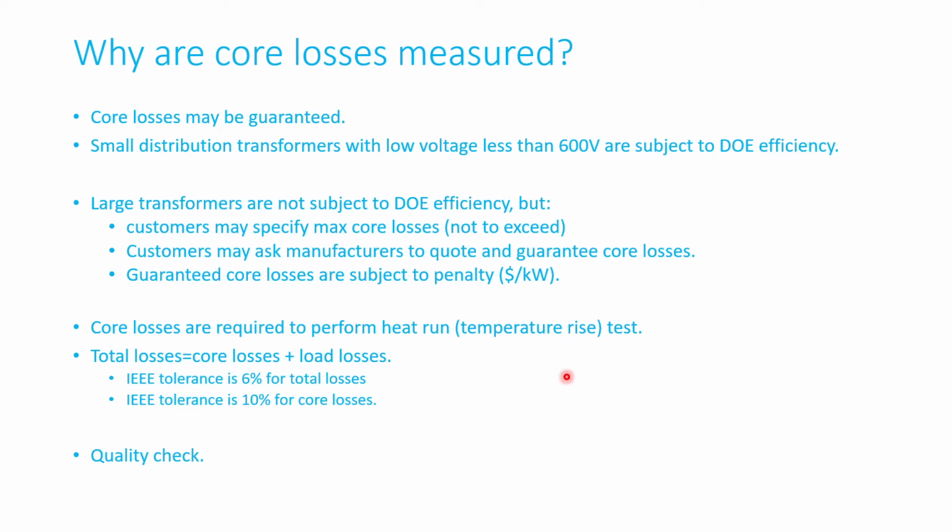They look like a cylindrical can. And they have to stamp on the nameplate DOE compliant. So it's like a must. If the transformer does not meet DOE efficiency, basically the Department of Energy publishes efficiency values that they have to meet per kVA, so they have certain criteria.